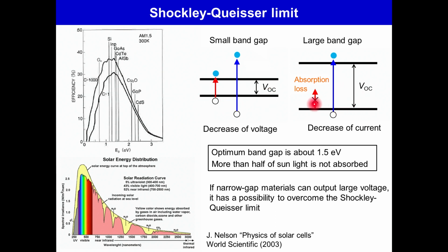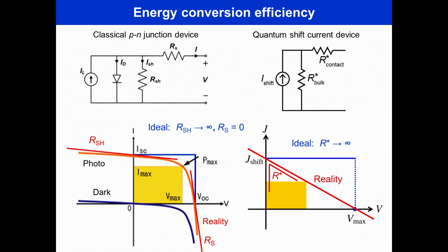While the coupling is strong, when the red light hits, the red light has less energy. So the electrons cannot go up, which means that the red light cannot be absorbed, so this is a loss of energy. This is the limit of the generated current. That is, the limit of these semiconductor solar cell principles is that the efficiency is about 35% at the very limit of the voltage limit and the current limit. In the best case scenario, and in the instance of very ideal results, it is actually possible to achieve this level of efficiency. Additionally, the circuit diagram of an ordinary solar cell shows that the current that can be drawn from the cell is proportional to the intensity of the light.